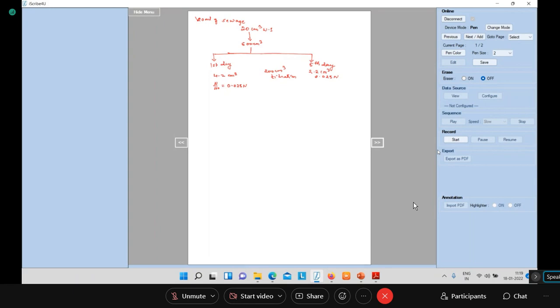The principle behind this calculation is the Winkler iodometric method. Same calculation you have to use. To calculate the DO on the first day, you just use N1V1 = N2V2.